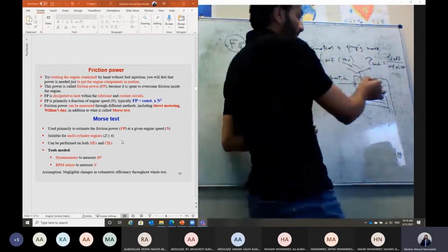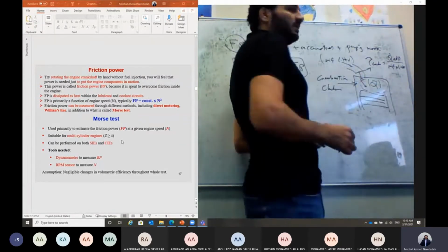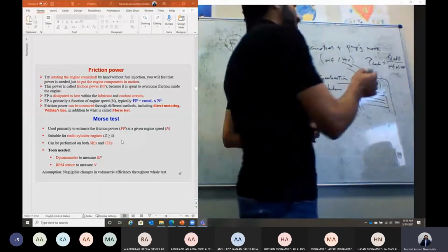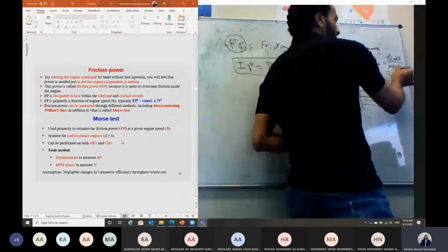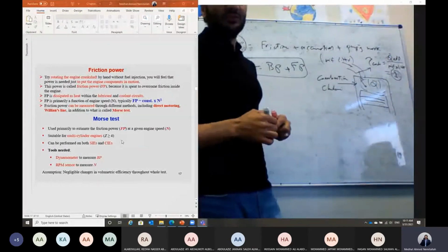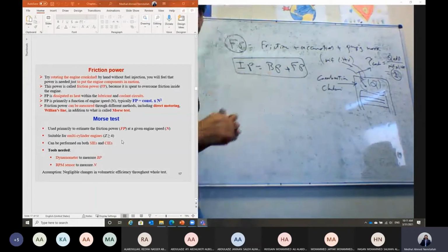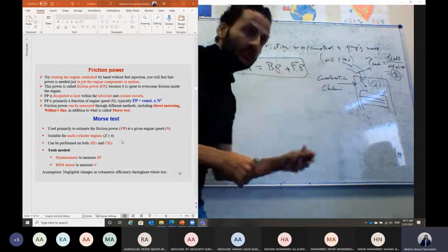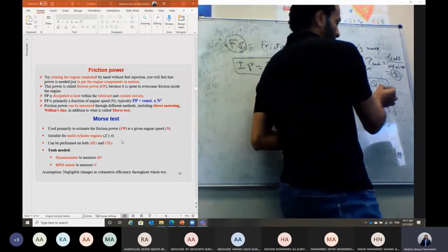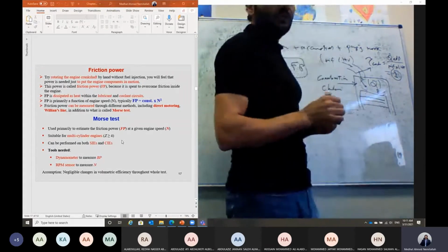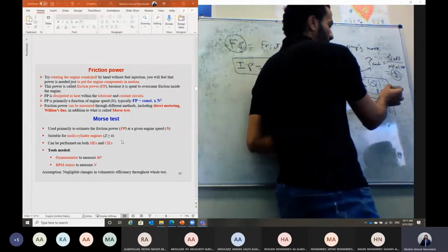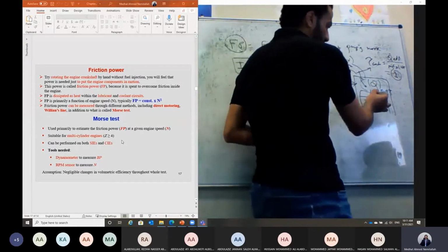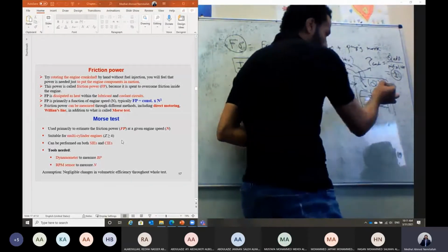As we said, we cannot guarantee that all of the fuel, all of the chemical energy, will be released and converted to thermal energy in this case. But in most of the performance analysis of any engine, we just assume this combustion efficiency is equal to 1. Okay, so we assume all of the chemical energy will be converted to heat. And once we have heat here at the minimum volume, this will result in an increase in pressure and an increase in temperature as well. This increase in pressure and temperature will press the piston down, and it will apply indicated power.